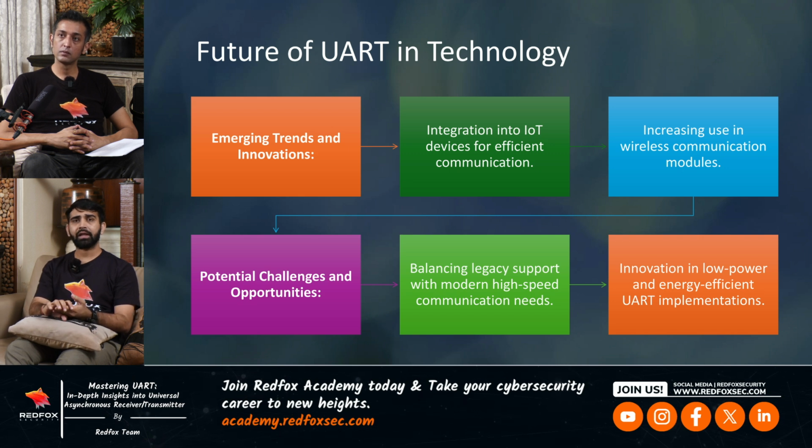UART pins are already there in the devices, and for emerging integrations in IoT devices, UART is compulsory. If you want to secure it, more challenges come up. From the vendor's perspective, before supplying the device to the consumer, they have to cut off or disable the UART pin sections.